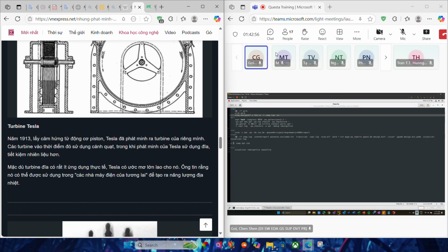Then after compilation, in the optimization phase, we have vopt test, which is our top instance. And there's also a suppress here for a suppressible error. And -pa_upf_version, here we specify which PA version that we are using. In this case, we are using 2.1. And then to load UPF in, we use -pa_upf new.upf.